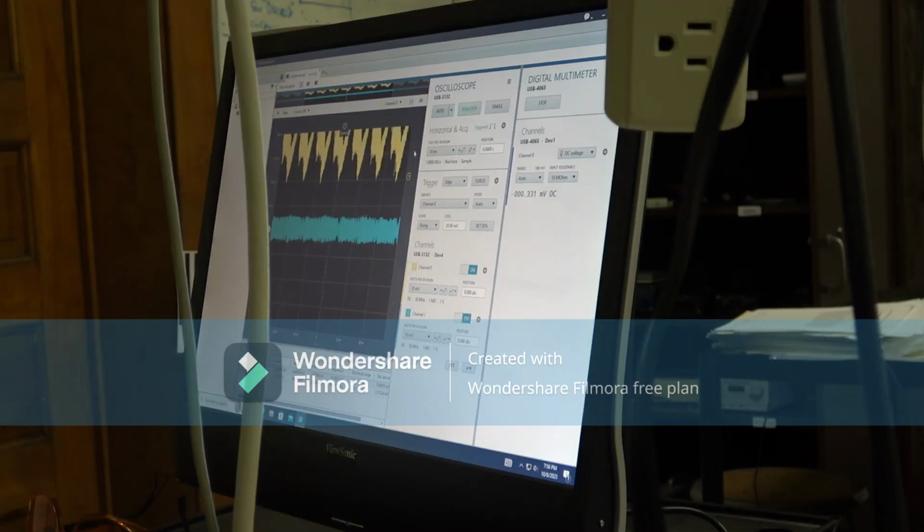So after mounting and optimizing the photodiode position, we will adjust the phase between the chopper and photodiode signal. The purpose of it is to synchronize the signal from the chopper and the photodiode. Then we develop a calibration curve of the photodiode to relate the photodiode output voltage to the power of incident light, and then we will determine the linearity of the photodiode, to check whether the photodiode operates linearly with respect to the incident light or not.